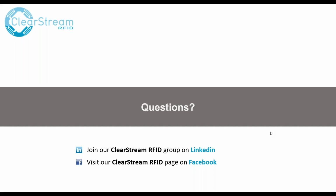With sessions, you get different types of sessions depending on what you want to do. Going back to how it was mentioned in the question, basically what happens is the reader goes out and says, okay, how many tags are out there? Give me your EPC or your unique ID. Some of the tags respond, and the ones that do respond, the reader puts into a mode where they cannot communicate any further for a limited amount of time. In that time, the reader goes on to read further tags that may be in the read range. And this is where the sensitivity and chip performance comes into play as well.